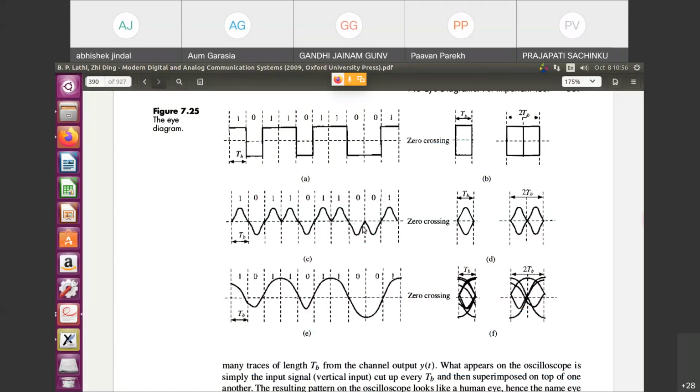It might be that you have a big stream of ones, but generally this is avoided by channel coding or some sort of coding where you avoid long streams of 1s or long streams of 0s. So you can assume that there is a healthy distribution of ones and zeros in the bit sequence, or the line code which you are receiving, and hence you will have both the shapes.